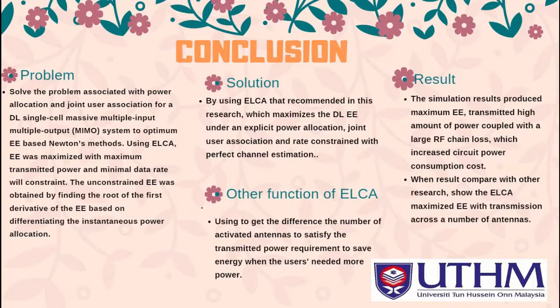Using ELCA, EE was maximized with the maximum transmit power and minimal data rate constraints. The unconstrained EE was obtained by finding the root of the first derivative of the EE, based on differentiating the instantaneous power allocation. And as the solution, the ELCA recommended in this research maximizes the DL EE under explicit power allocation and joint user association, constrained with perfect channel estimation.